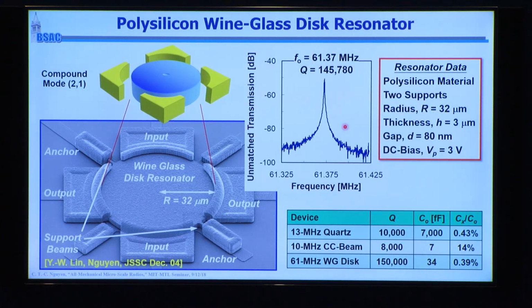And so I'm about to show this, but what I'm about to show is going to use this device here that now has 4 electrodes around it. It actually has a mode shape that looks like this, so it sort of expands and contracts along orthogonal axes. And 2 of these electrodes I'm going to use for filtering. 2 of these electrodes I'm going to put in a positive feedback loop to create an oscillator. But before doing that, let me just mention a few things about this technology and why it made so much sense for oscillators. So why do these companies do so well with the oscillators?